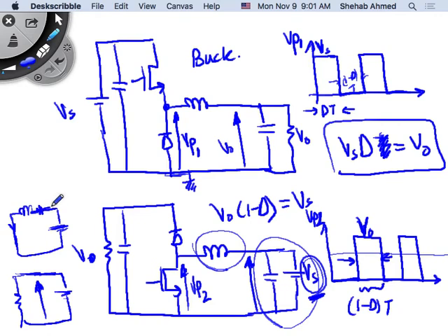No, because this typically has a certain value of resistance, and this typically has a source limit. A battery is rated for a certain amount of current that it can push out. You cannot withdraw an infinite amount of current from a battery. A battery has an equivalent circuit that typically looks like an ideal source with a resistance in series. So regardless of putting a short circuit in here, you will be limited in the amount of current due to the ideal source. There is a limit, right?